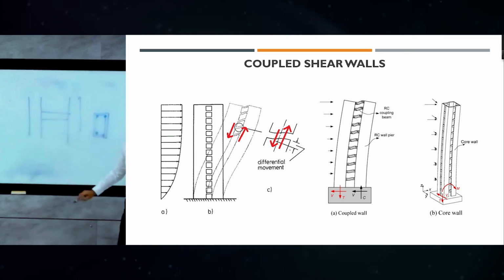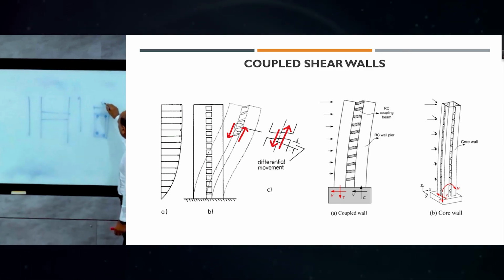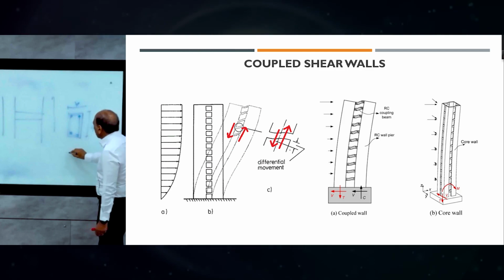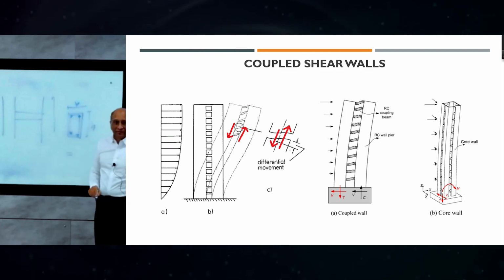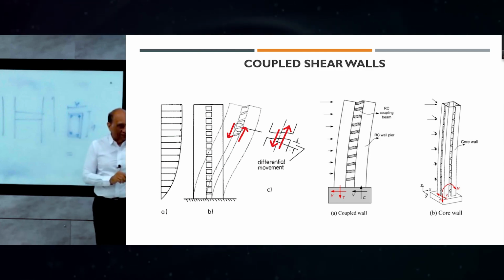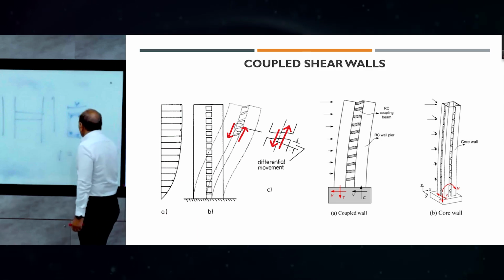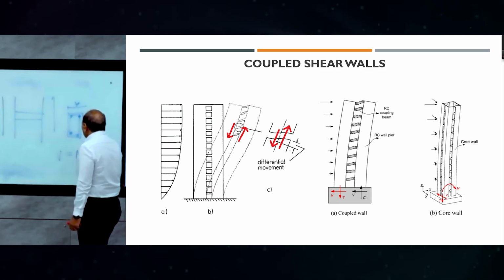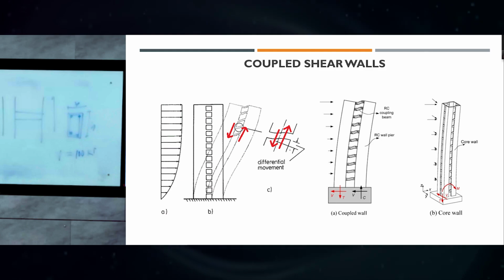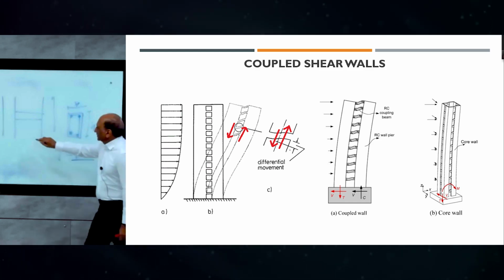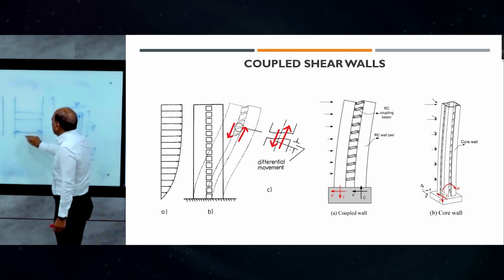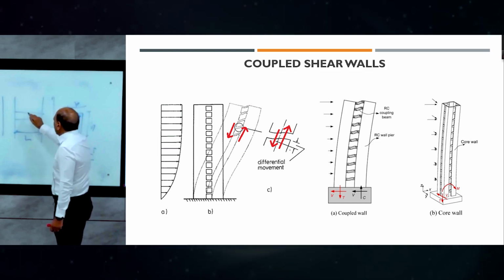So this is the section of this beam. It has a width of B and H, and it has a shear capacity. If you calculate the beam, you can calculate the shear capacity, right? So let's say the shear capacity is equal to 100 kilonewton, the maximum shear it can take based on the size and the maximum reinforcement that you can put, right? Capacity from the code. So now you know that. And this is the length, let's say, L.